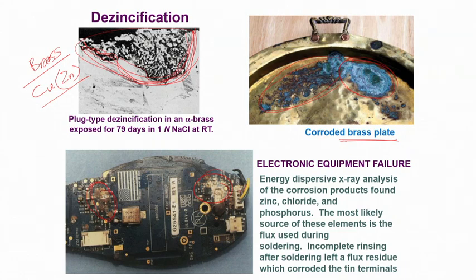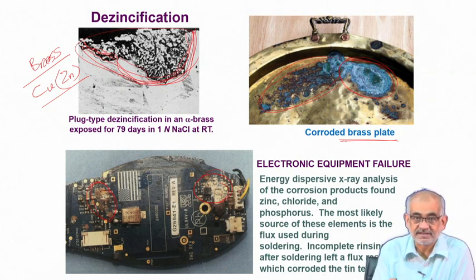Actually, we are all aware that in microelectronic devices, locally at a particular junction, the voltage can be fairly large, and the current flow in a limited region could also be fairly high. So it can cause local heating, and in fact heat dissipation. For heat dissipation, we do allow airflow as a means of heat extraction. We also must realize that the whole electronic circuit is embedded in a package or a polymeric substrate in which all these electronic components are embedded.